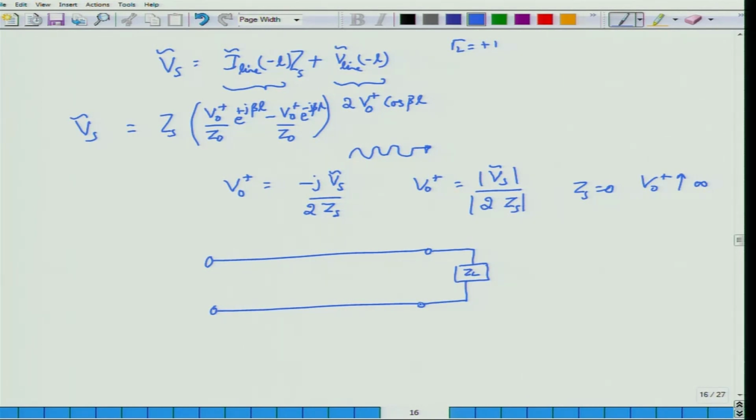If I do not make any crooked shapes, it does not mean that I am considering the lengths here as transmission line, it is just that I did not want to draw crooked lines all over the place all the time. So, I consider this transmission line terminated in load ZL. Let the transmission line have a certain characteristic impedance of Z0. To this I connect the source having an impedance of Zs and generating a certain phasor voltage Vs bar. How do I solve this problem?